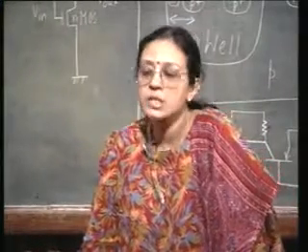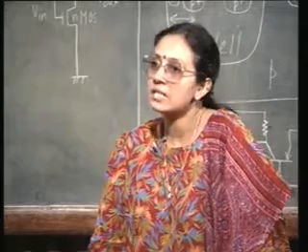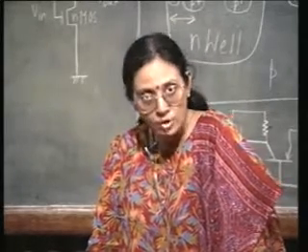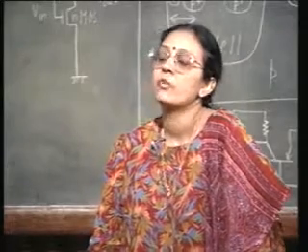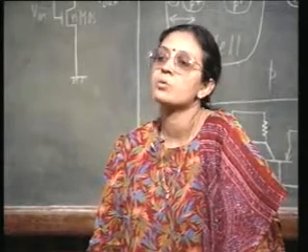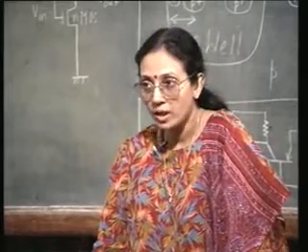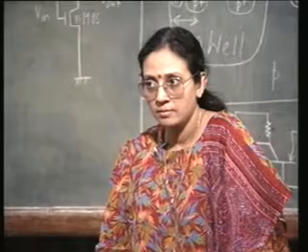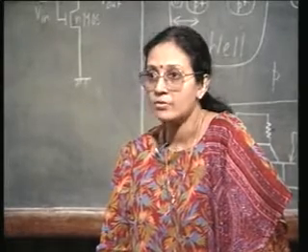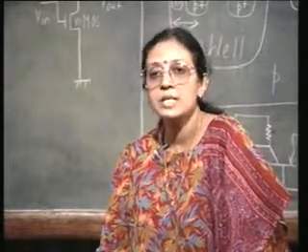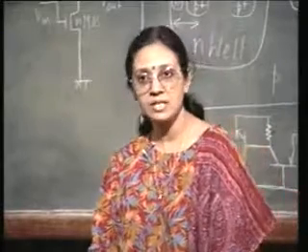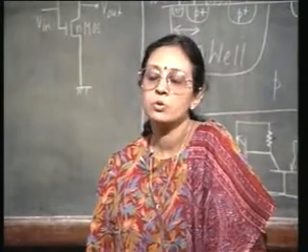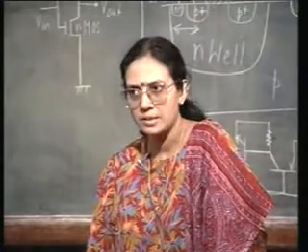What I mean is, you see, so far we have seen there is a great difference between the bipolar junction transistor technology and the MOS technology, in the sense that for MOS devices you have to use only bulk wafers. So far we have not used any epitaxy. So far we haven't used any epitaxial layer for MOSFET, right. So, we say that MOSFET is always a simpler technology because epitaxial wafers are horribly expensive.